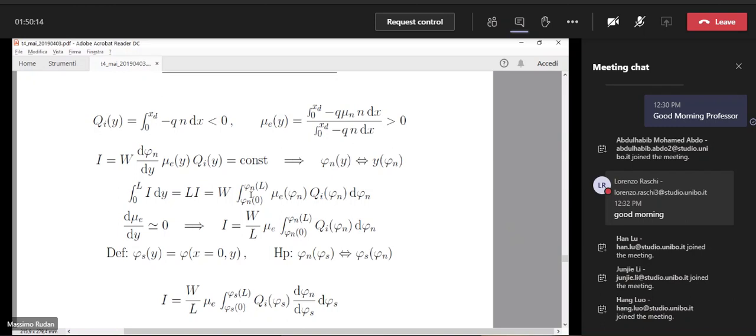Here we define the surface potential in the MOS transistor exactly in the same form, but here the potential is two-dimensional because it depends on x and y in general inside the device, okay? So when we fix the position of the surface, x equal to 0, the corresponding surface potential still depends on the position y along the channel. So we have phi s depends on y.